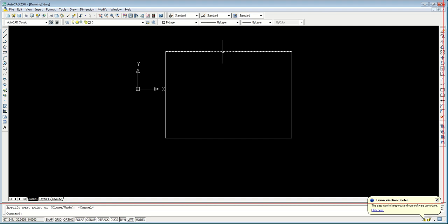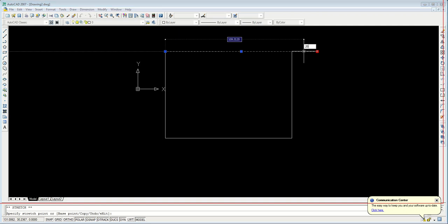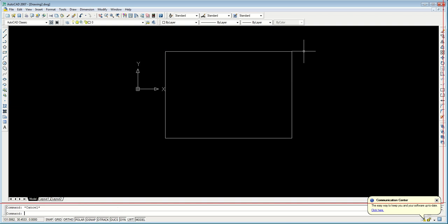If I go to one of them and click on the line, you will see three blue boxes. If I go here, I will see the dimension of that line, and this one and this one, the end of the line and the beginning, are called extension points. So if I click on it, I can extend my line further or reduce it. For example, if I draw a 100 but my line is not accurately 100, I make a mistake and it is 120, so I write 20, then my line is now 120, which is what I want from the beginning, for example. And if I want to reduce it, again I will write the reduction dimension that I want, not all of them. So if I write it and enter, then it will give me the correct line that I want.